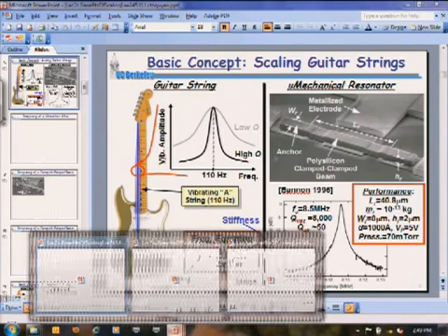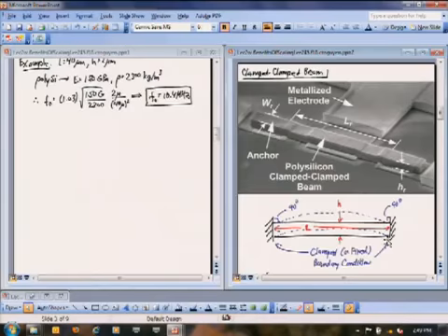Well, there's a lot more going on than just our ideal beam. This is our drawing of the beam, which was analyzed to get the equation that I just wrote for you. First of all, there are width effects, like you were saying, but they are not going to be that consequential because the beam, 40 microns long versus 8 microns wide, is quite a bit longer than the width. When you shrink it down to 10 microns long and it's 8 microns wide, then you start having to worry about other effects, Poisson effects and that sort of thing. But that's not the case here.